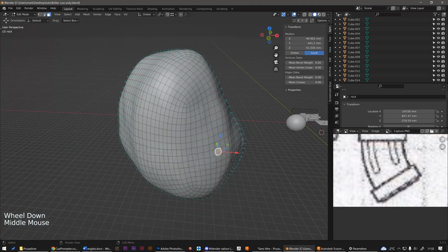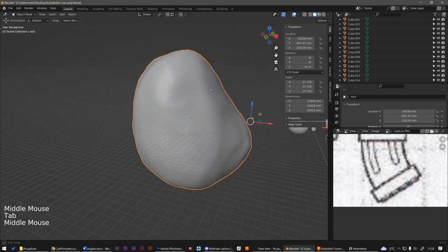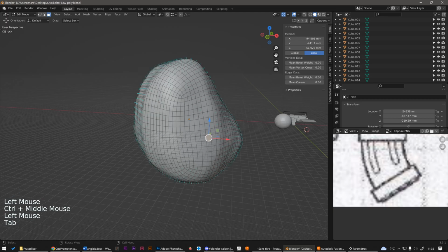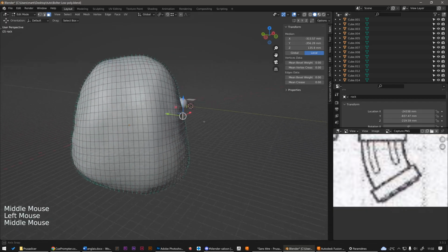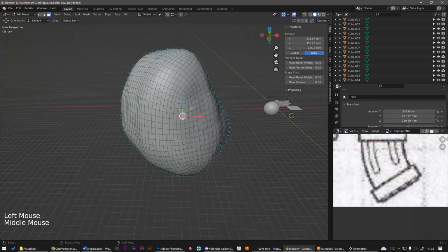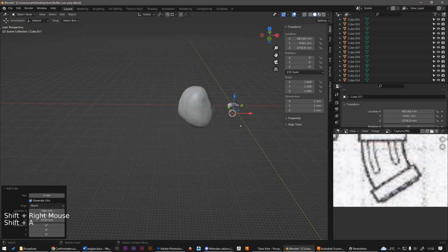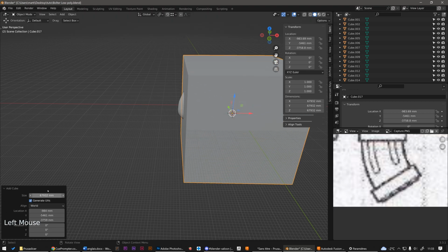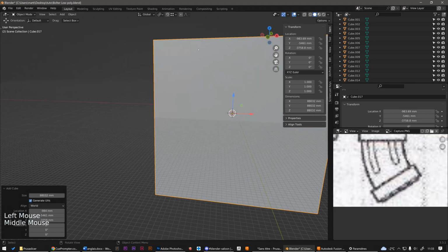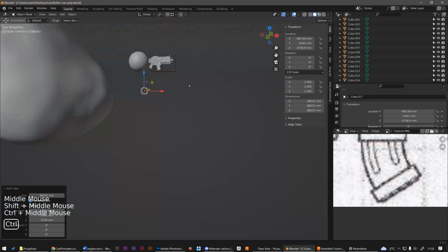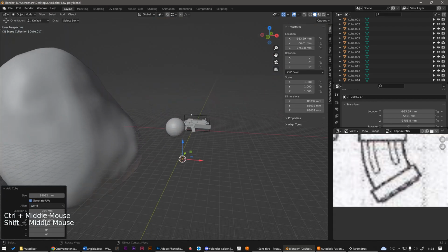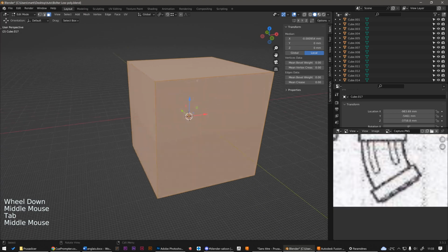So when we are modeling objects, we make sure that all the normals are well oriented outwards, so that all the faces will be visible from the outside of the object. On the other hand, if we model an environment, an envelope, like a room for example, if I want the walls to be visible when we are inside this room, we must orient the normals towards the interior of the object. For this, we can flip normals.